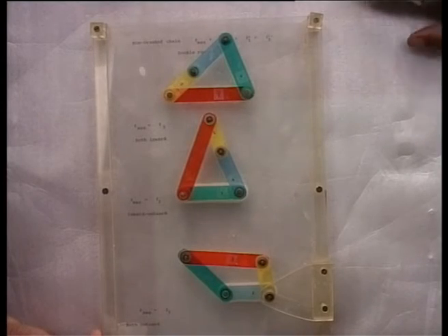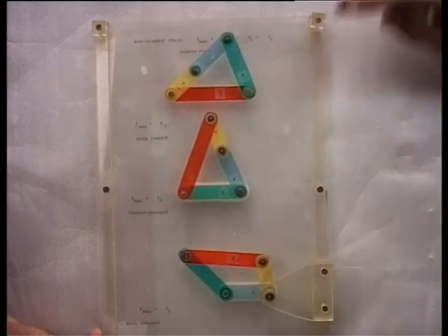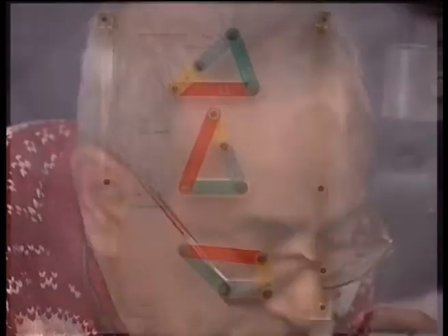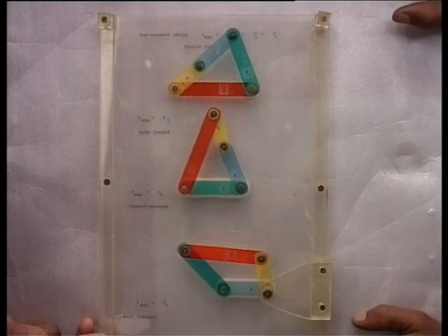As a result, such a non-Grashof linkage is not much useful in real life, because if it has to be driven by a motor, then there has to be a crank, whereas no crank exists in a non-Grashof linkage. Thus, only the Grashof linkage is useful in practice if it is to be driven by a motor, and the shortest link must be connected to the motor shaft.